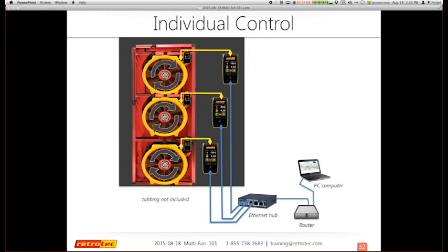For those who do large buildings, they'll actually walk around with a thermal imaging camera and see which fans are not at the same temperature. Then I know that one is actually not moving, or maybe moving in the opposite direction.